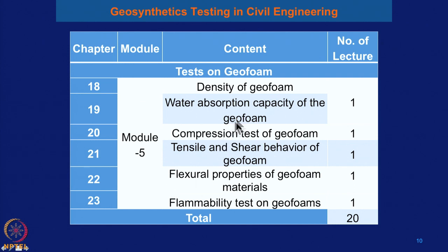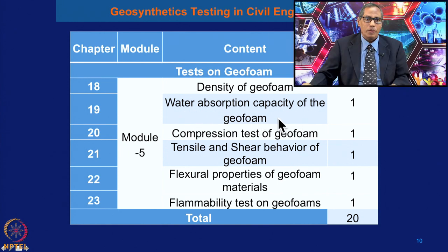These are some tests on the geofoam material, which is a super-light material. For chapter 18, we will determine the density of the geofoam material. Chapter 19, water absorption capacity of the geofoam, and chapter 20, compression test of the geofoam. Chapter 21, tensile and shear behavior of the geofoam, and chapter 22, flexural properties of the geofoam material. Chapter 23, flammability test on geofoam.